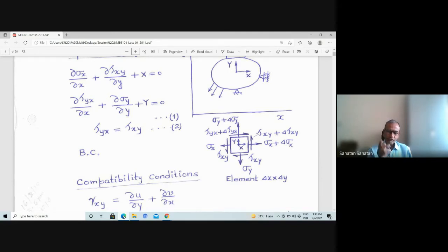For normal stress, a double subscript is generally used. So on the left hand face, sigma x is indeed sigma xx: stress in the x direction, that's why it is sigma subscript xx. But it is common practice, for normal stress, we don't write both the indices, we write only the first index because they are repeated. Shear stress, obviously, acts on the x face in the y direction, and this is tau xy: x is the face identification, y is the direction identification. So this is how all the stresses are identified, and thereby one can understand which face it is acting on and in which direction.